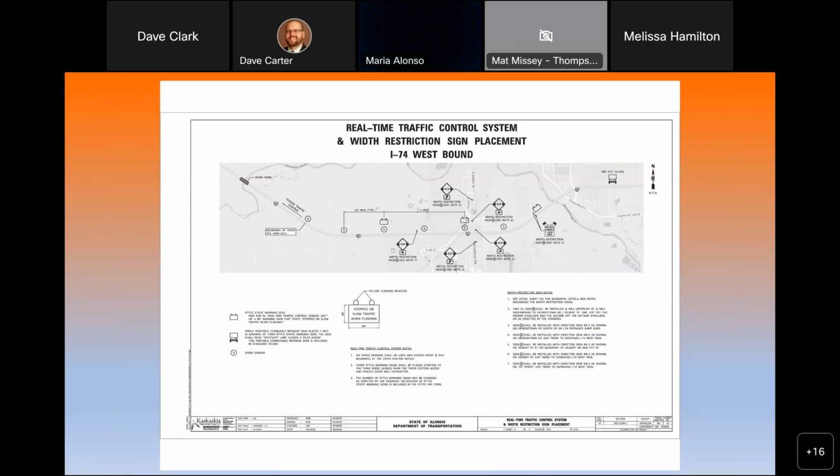Keep in mind, if you're doing traffic control and you're signing a project, you're going to want to go with the RE. They're going to probably lay it out ahead of time. They also have a traffic engineer that usually comes out and looks at these and helps lay out the signage, because you don't want to put a sign where it's behind something and people can't see your construction sign. So these give you an idea where they're going to be located, but they may get moved a few hundred feet one way or another to get the best fit and the best visibility.